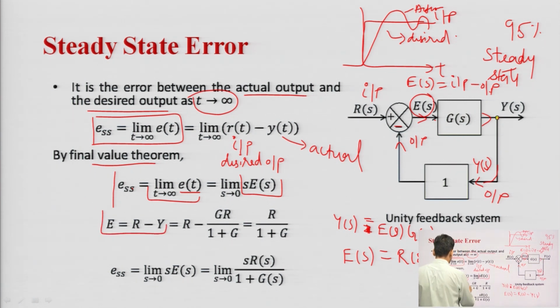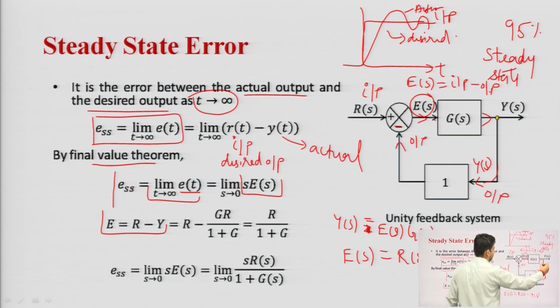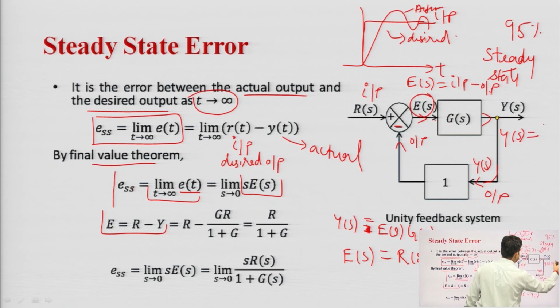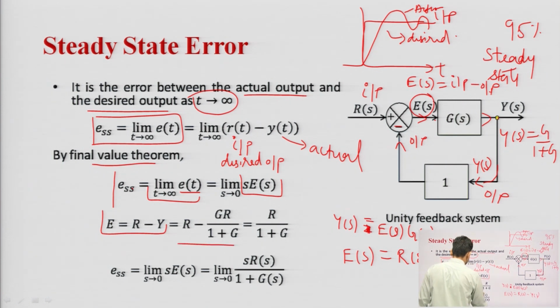Okay. So, R is here, what would be my Y? If I solve this transfer function, Y(s) over R(s) gives me G over 1 plus G(s)H(s). So, H(s) is 1, this is G over 1 plus G. Okay. Right now it is multiplied by the error term, the G term. So, it will be multiplied by R, and further if you simplify it, this will become R over 1 plus G. Okay. So, if you solve it further, you will get the expression for E_ss.